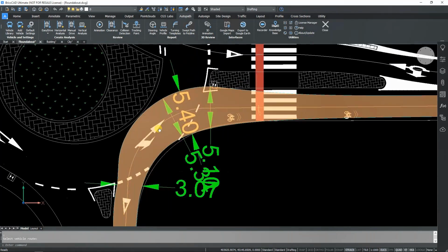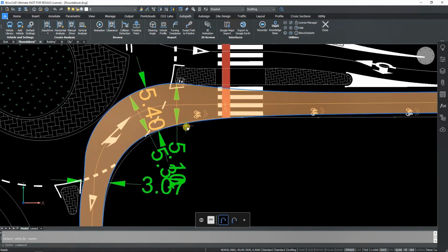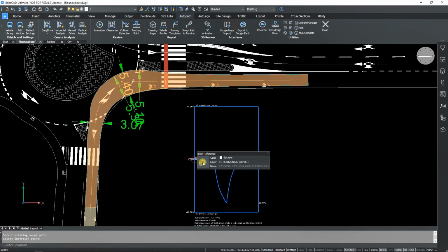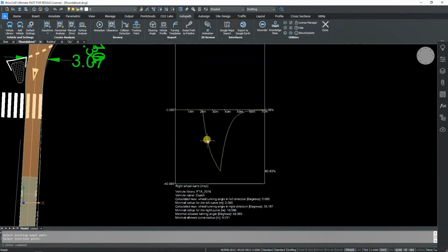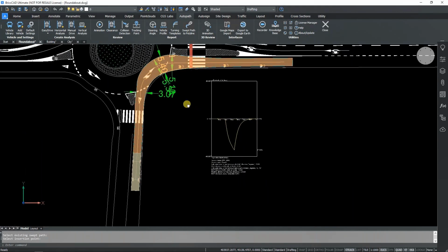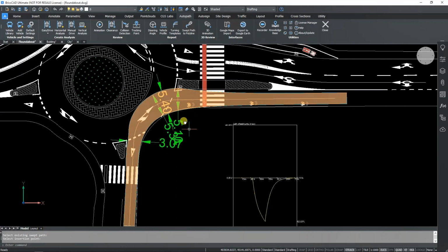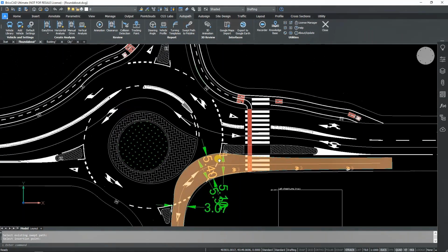And here we can see, okay, we might have interferences with this curve or this pavement, but another thing that we need to generate is to check whether the trajectory that we planned is feasible for the vehicle. And this is a report that shows us the different turning radius of the vehicle at each point. We will comment on this a bit later, in more detail.